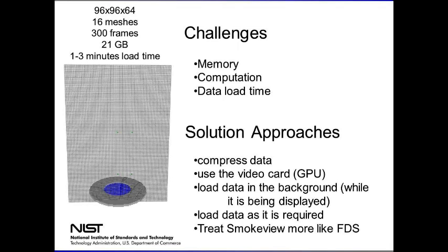And what load data as required means is that there's a new feature in Smokeview that if you want to render a frame, you only need to render the data for that one frame. You don't have to render the whole thing. So you don't have to have a computer with large enough memory to visualize the whole case. You only need a computer with large enough memory to visualize that one frame.